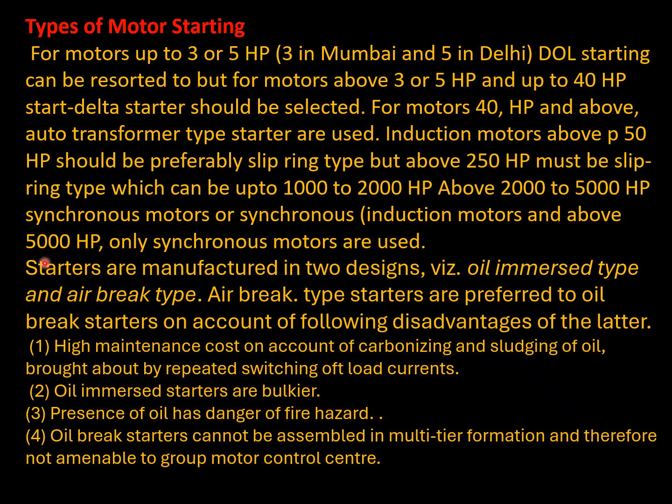Starters are manufactured in two designs. One oil break type and air break type. Air break type starters are preferred to oil break starters on account of following disadvantages of the latter. First, high maintenance cost on account of carbonizing and sludging of oil brought about by repeated switching of load currents.